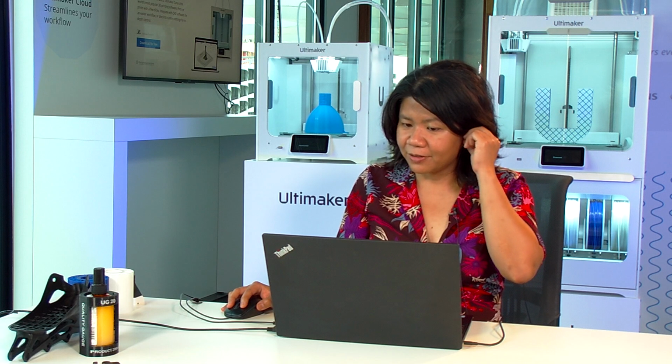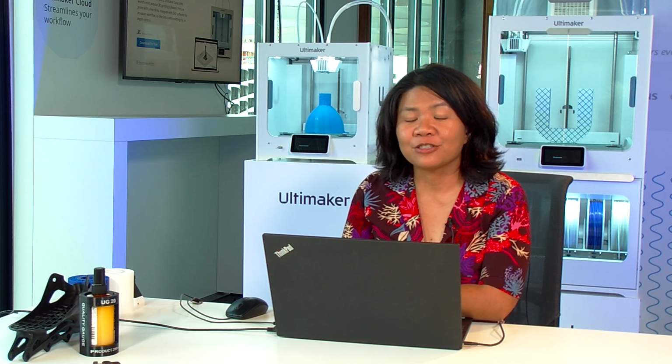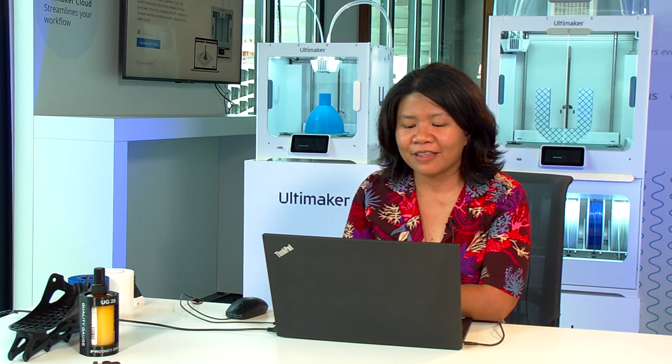So now we're going to take a look at the support strategy component. Now we're going to talk about most of the slicing parameters in the next section here, but this one is worth having in mind from the very beginning. So, Terri-Ann, do you want to get us started with how you think through support settings? Yes. The best support strategy is no support. Because support adds time, it adds cost, and it also causes scars on the surface of your model. And people don't usually want that.